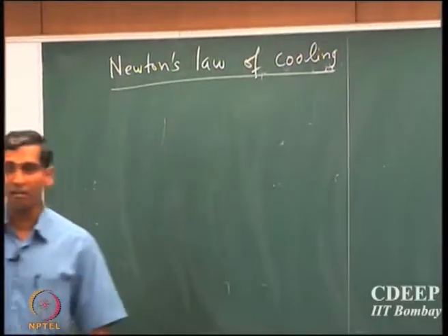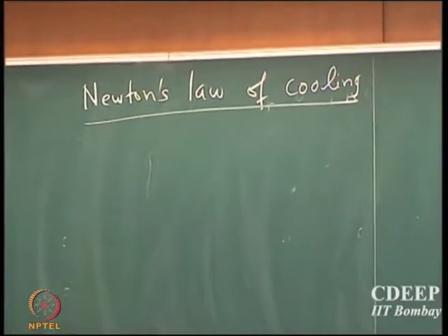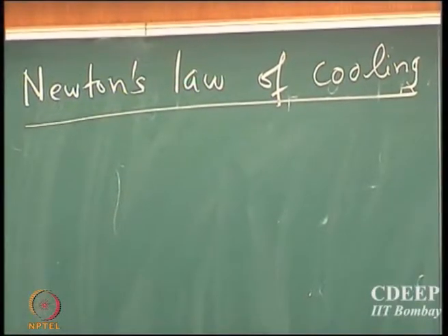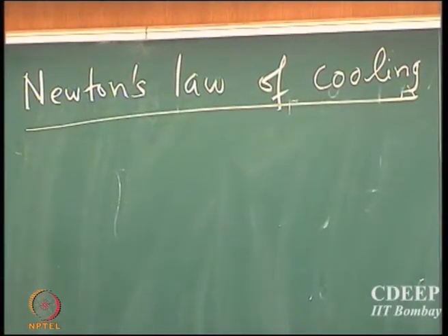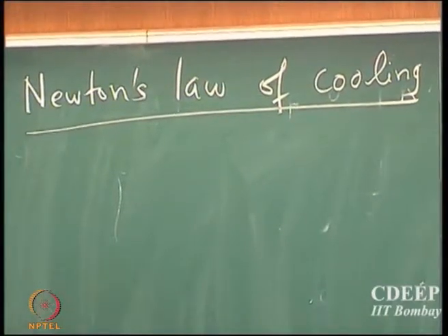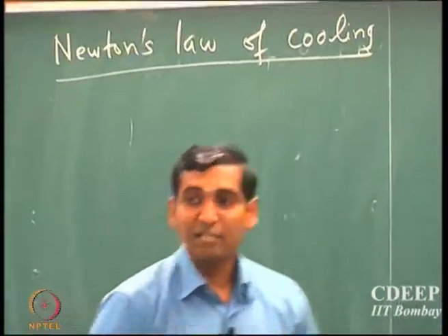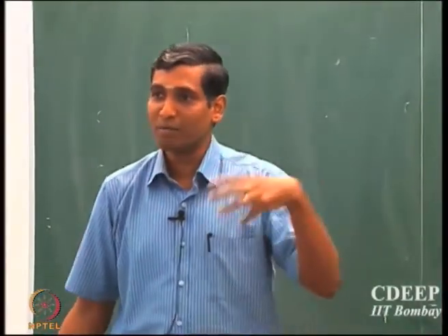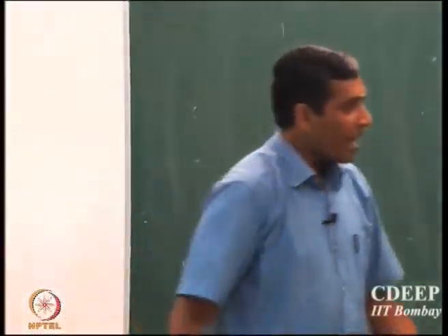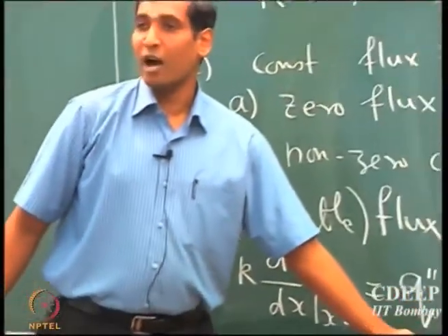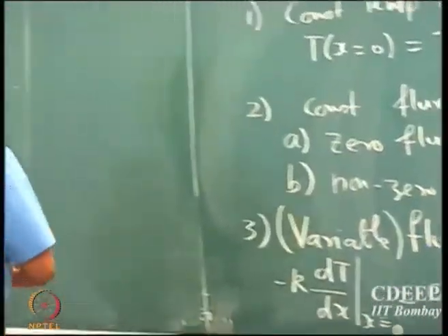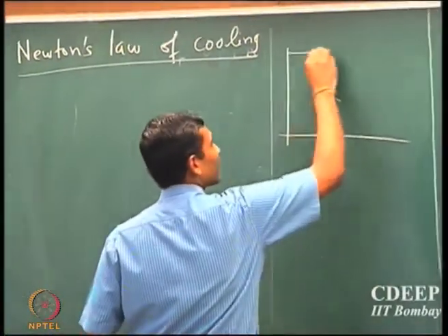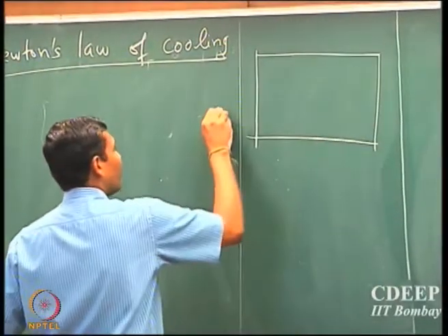Similar to Fourier's law, which is the constitutive relationship between the flux due to conduction and the local temperature gradient, Newton's law of cooling is the constitutive relationship for heat transport from a solid system where conduction is the mode of heat transport inside and there is convection outside the solid. So the way to describe it is, supposing we have a solid here, and there is some fluid